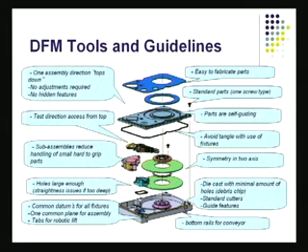Let's again take a look at that disk drive, and if you take a closer look at the screen, you'll be able to read a few things. For example, the assembly is to be done in a top-down manner, so that no adjustments would be required, no hidden features would be required. The test direction of axis also is going to be from the top. These are guidelines given to the design for manufacturing specialist.